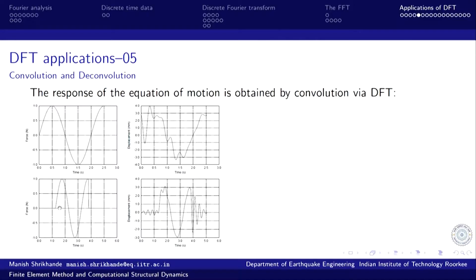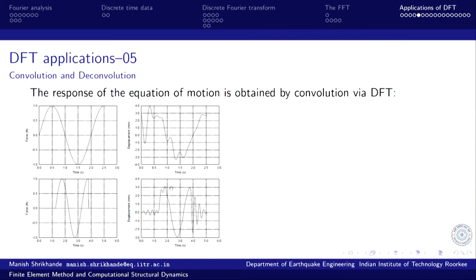And what happens? If I pad some zeros, let us say add some zeros in the front and some zeros at the back of the excitation. This excitation looks like a sudden start of this sine wave pulse and then sudden withdrawal, and after that it is 0. If I use this excitation and again compute the DFT and the inverse discrete Fourier transform of the Y omega, we get something like this.